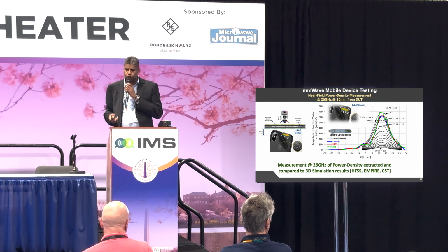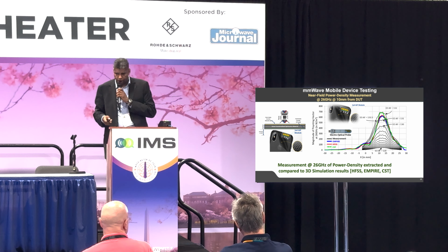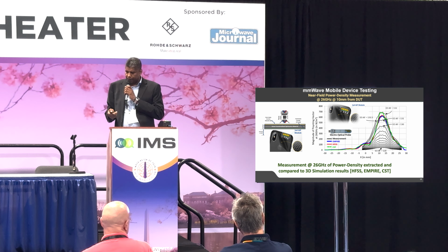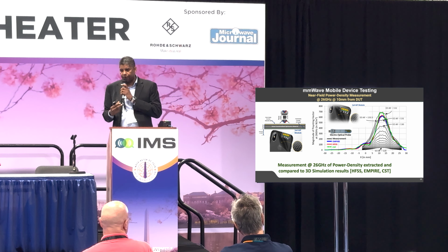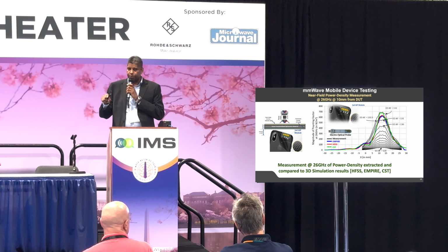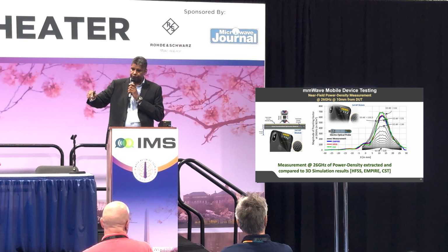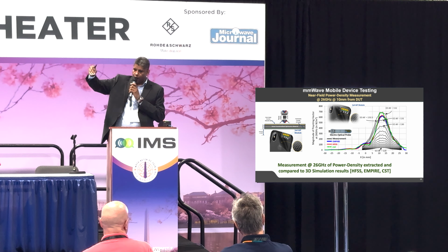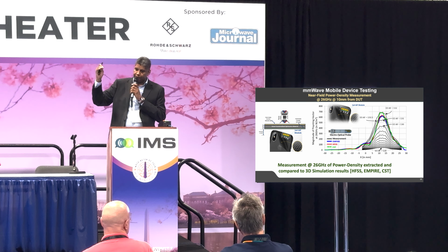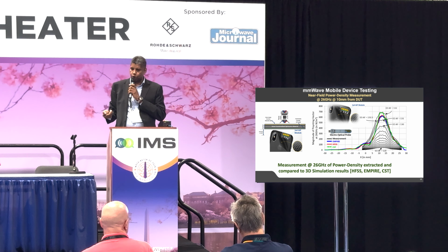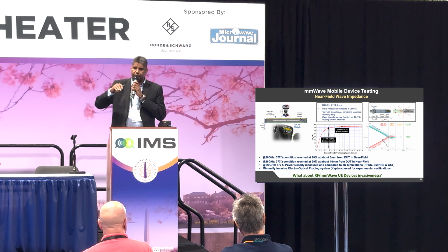So we pushed it actually at the next level of comparing the thermal near field measurements versus classical optical probing measurement techniques. And we even compared it to 3D full wave analysis from CST, HFSS, or Ampere. So CST is operating in time domain, CST and HFSS in frequency domain, but Ampere is also operating in time domain. So we were able to compare in the near field, the crossing of the antenna level, how the level of the pointing vector, which is actually linking it to the square of the electric field divided by the impedance. And we compared that in the near field at 5 millimeter from the DUT.